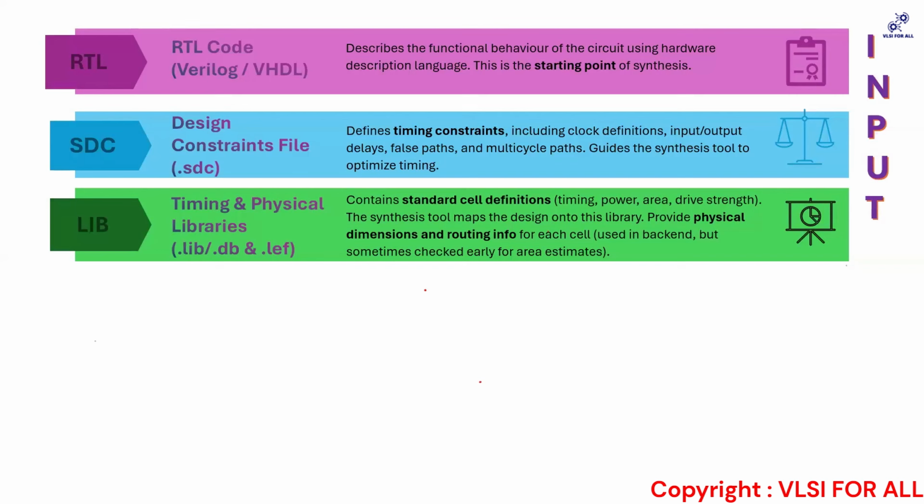As we go ahead, I'll explain what the different contents present in the timing libraries are, and what the contents of the physical libraries are. Along with this, you can also consider one more file, the tech LEF, which we call the .tech LEF file, which is technology LEF. It is provided by your foundry, and these libraries are also provided from your foundry or fabrication unit's end.